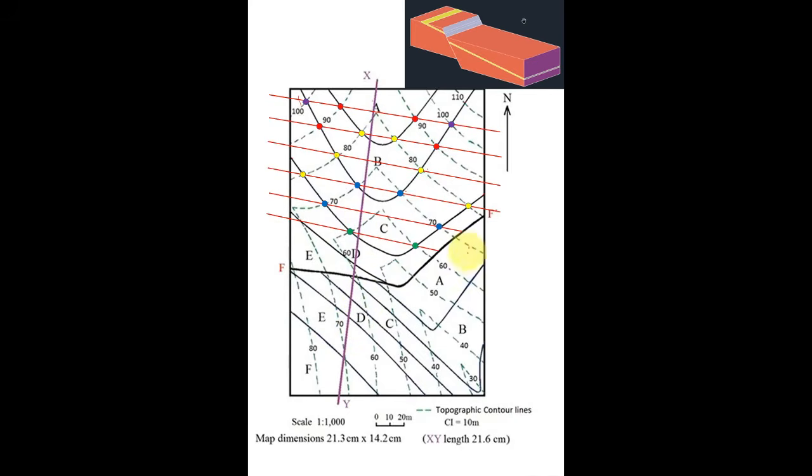And if you see, I am not taking these strike lines across throughout, because this F dash is a fault and it has divided the entire rock mass into upper rock and this lower rock. So I'm not taking these strike lines into the lower rock, as I already told you that I'll be showing them in a different color, just so that we can distinguish properly.